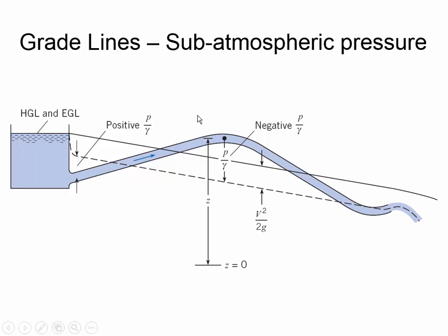It doesn't matter if the pipe is going high or if it's wiggling back and forth. The decrease in pressure is constant, and it's a function of the friction in the pipe. And the same thing is true of the energy grade line, that there's a consistent decrease due to the pipe friction, but it may be that inside of the pipe the pressure is positive, and then because of the height getting higher and higher, you may have a negative gauge pressure. But even if you have a negative gauge pressure, you're still losing energy inside of the pipe due to the friction losses. And then the thing to see at the exit of this pipe is that you always should have the HGL terminate at the open surface of the water. And then here, since it's a jet that still has velocity head after the water exits the pipe, then the EGL is above the water surface after it exits the orifice.